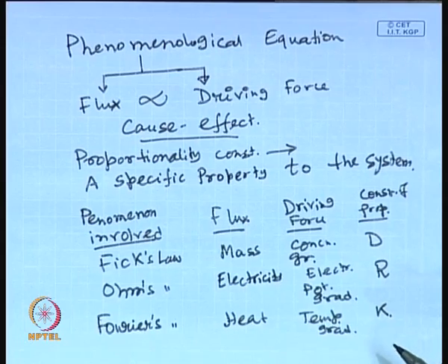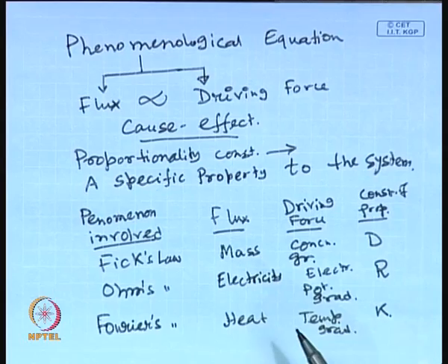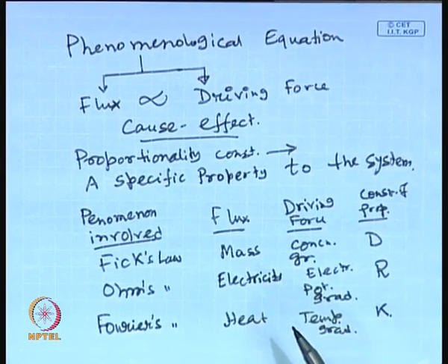In membrane based separation processes, we have several driving forces. For example, the main driving force is chemical potential, but chemical potential is an abstract thing. It generally has three components for a neutral solute, as we have discussed earlier: concentration, pressure, and temperature. Now, these driving forces may be interdependent or they may be absolutely independent. Okay. Now, let us look into the cause-effect relationship in membrane based processes.